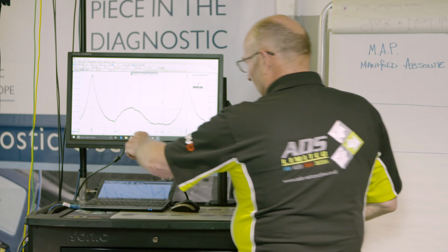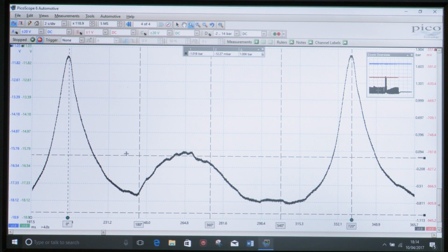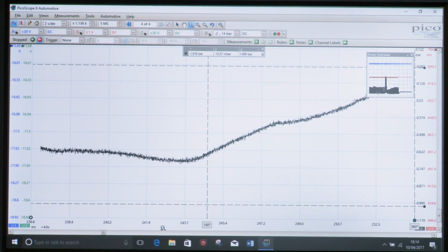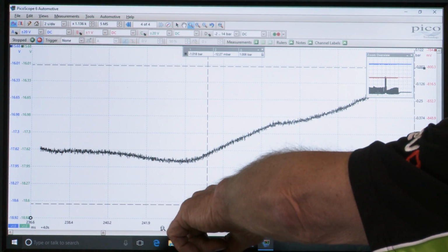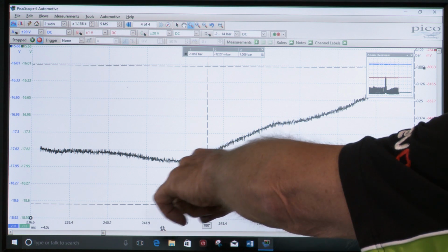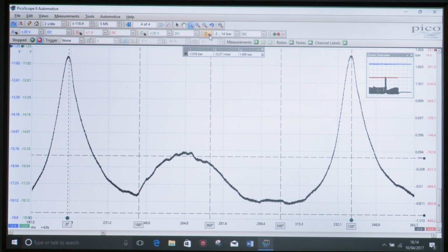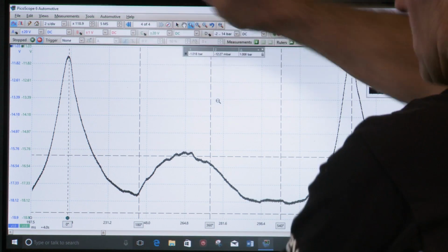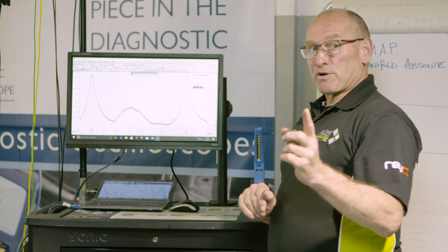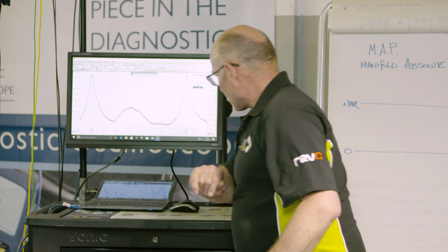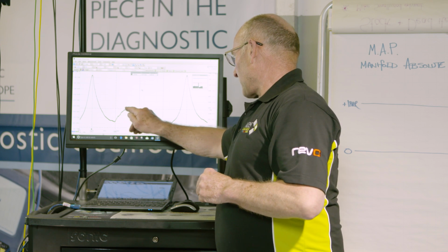So, what's going to happen here? This is the bottom of the stroke. Now, if we're being picky, I'm just going to draw a little temporary box around there. Whoa! If that piston is still coming down, this is the bottom of the stroke, why has the pressure started to increase? Surely that's not possible. I've just made a statement that in an expansion of area, the pressure drops. Yes, it does. There's the proof. It's still a pressure. So why has it started to rise before the piston meets absolute bottom dead centre, before it comes up on the exhaust stroke?